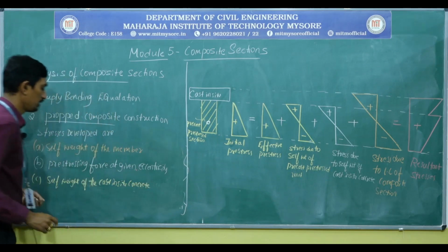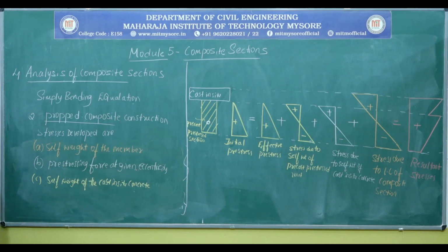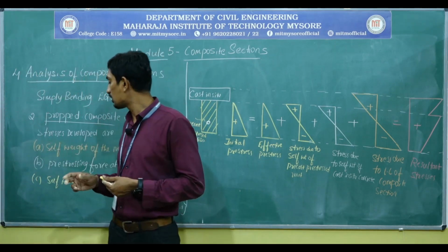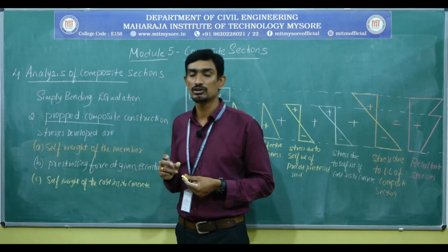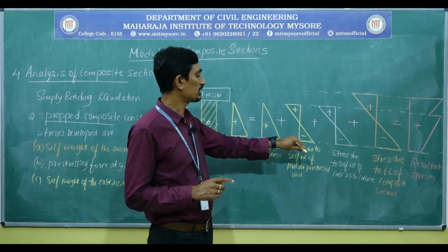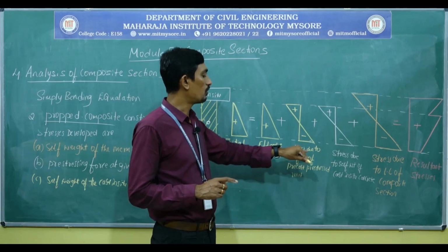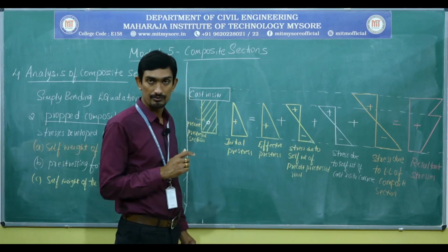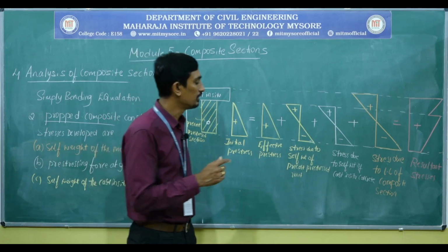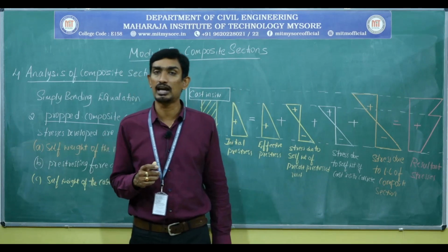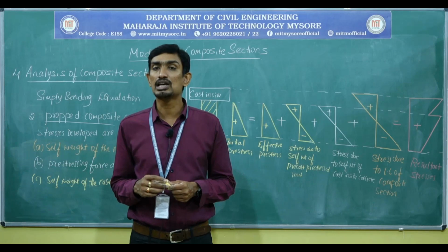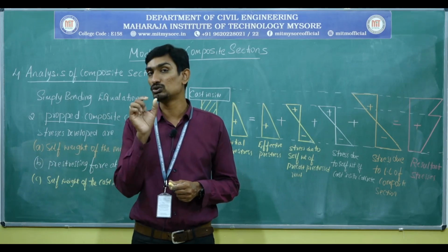In the stresses developed due to the self-weight of the cast in situ concrete, this is the one change you are going to come across in the case of propped. You can see the stresses encountered in the case of cast in situ concrete in the unpropped case. Now, for the propped case, the stresses encountered for a cast in situ concrete slab will be considered based on the composite section. Please note this point.